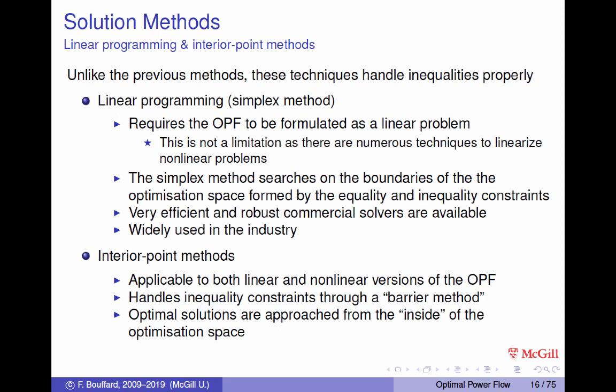Interior point methods, you will see those being used for both linear and nonlinear versions of the OPF, and they are what we call barrier methods, which penalize the non-satisfaction of constraints as part of the objective function. But the idea is that the optimal solution is approached from inside of the optimization space up to the point when it gets to the boundary.